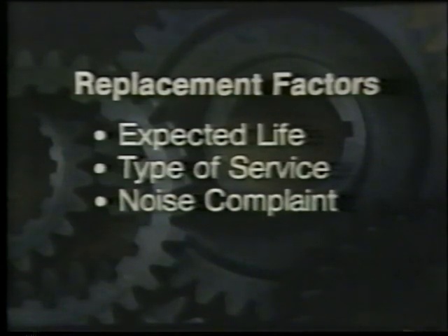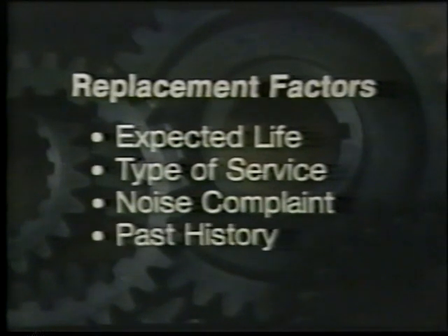Another factor is noise. If a noise complaint has been traced to a particular gear set, the noise may be a sign of future trouble. The entire gear set should be replaced, regardless of its appearance. Finally, if you don't know the past history of the transmission, its application, any previous noise complaints, its expected life, then questionable gears should be replaced.